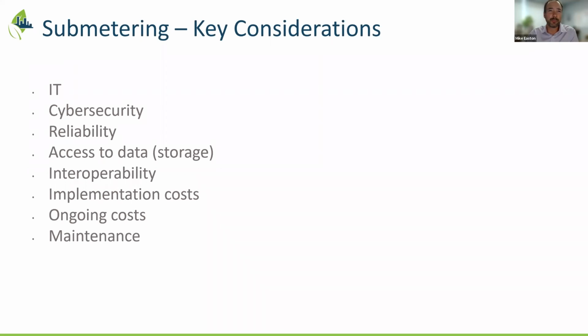And the companies installing them, whether it's contractors or meter specialists, are getting more experience with the equipment as well. So the equipment itself is being deployed better, more accurate with, say, less straight run necessary, and the installation and commissioning of them is also being done better than it historically has been. So the clamp-on and insertion industry in general is getting better, and that's allowing more flexibility in the meter installs.